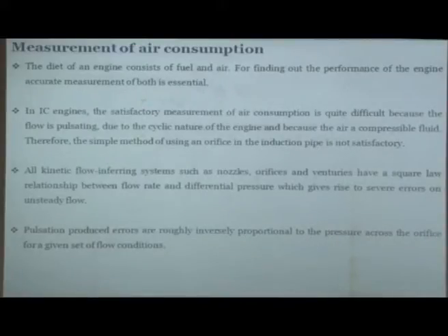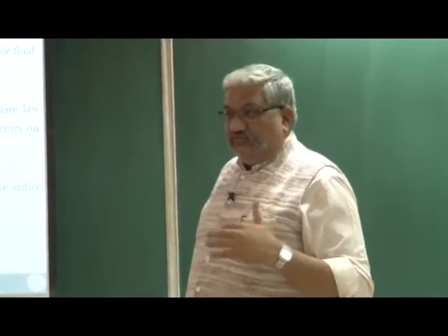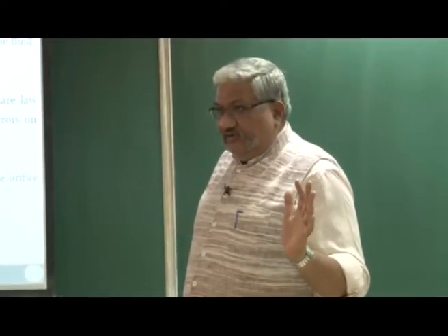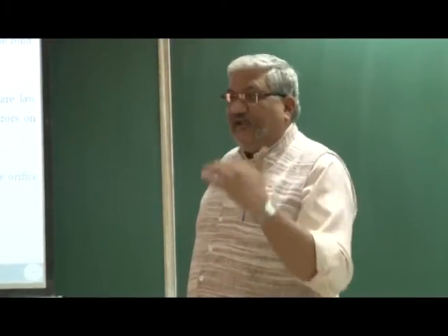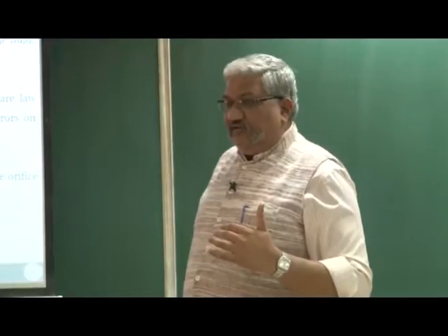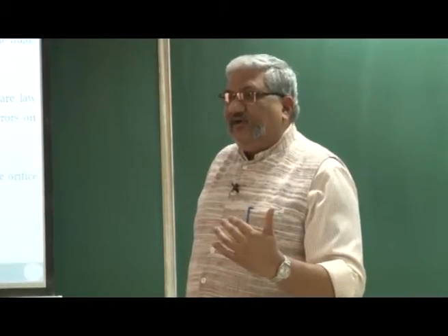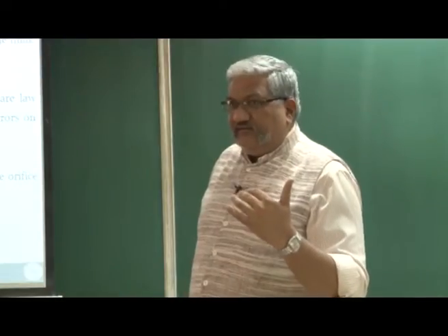So, in an engine, first you should understand, when do we take the air in? Only in the intake stroke. So, for the other 3 strokes, the intake valve is closed, right. Even in one stroke of the engine, in the intake stroke, what is the rate at which air is coming in? Is it the same or is it changing?